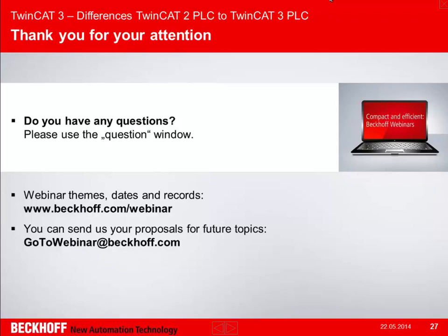Will performance increase with switching to TwinCAT 3? Yes. We have a new compiler. The new compiler is more optimized. It's not 100% faster than the TwinCAT 2 code, but it's dependent, of course, on the code. It's a few percent faster with TwinCAT 3 than with TwinCAT 2.